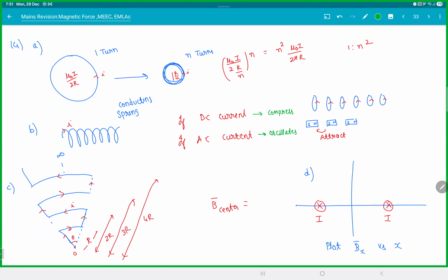And when you have some coil or anything, and you send a magnetic field through a metallic body, there will be random currents generated, which will produce eddy current losses. There's a third thing called hysteresis loss, which we removed from the syllabus. But whenever you try to magnetize and demagnetize a substance, it produces heat. It is called hysteresis loss. So there are three types of losses there. If you take a metal, send a magnetic field and try to make it a magnet, all the poles will turn in one direction. When you remove that field, the poles will turn back. In this process of turning the poles back and forth, you produce heat. This is called hysteresis loss.